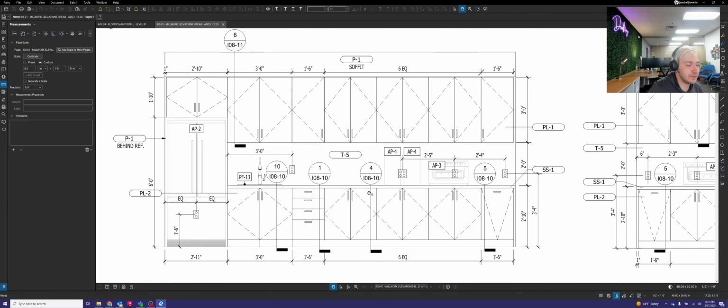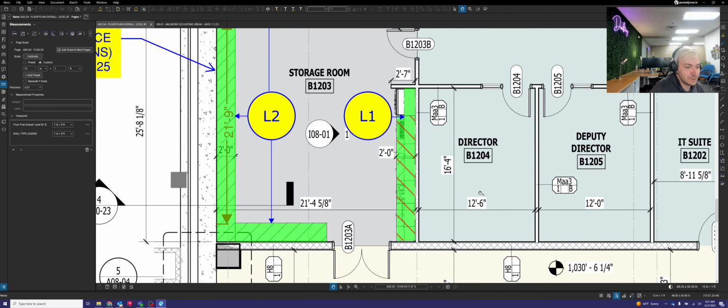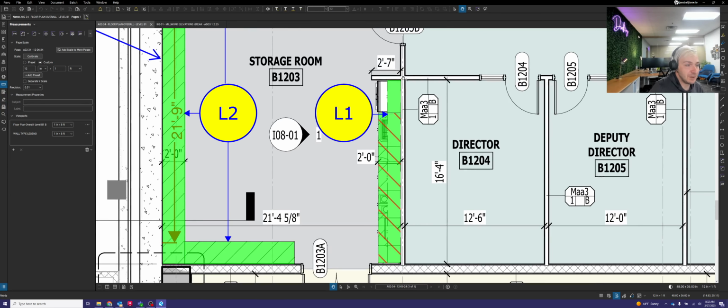Specifically, let's take a look at some of the dimensions that we're given here. Right away, we can see that we have a filler. Sometimes an architect doesn't always draw the fillers in, so you do have to keep note of that. If you don't see one on an architectural, but you know you need one, you have to add it in yourself. This architect actually does have it drawn, so that's great. There are fillers here on the left and the right-hand side. If I go back to my plan view to confirm that we actually need those, it looks like there is a wall. That would be what this is. We have a wall on the left and also the right-hand side of these cabinets, so we definitely will need a filler between our cabinet and that wall.